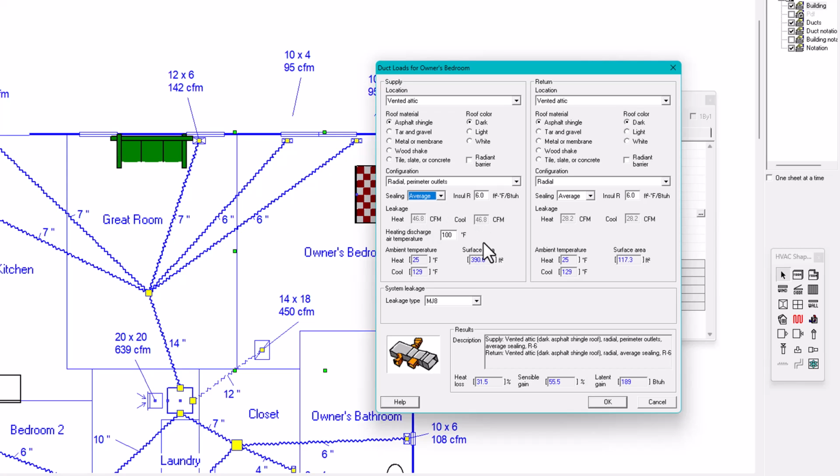And also, what is the insulation value of these flex ducts in the attic? That's also very important. In here it says insulation R6. I wouldn't think that would be a good idea, because in the attic we've got to be careful. But who says that? What we can do is check the energy conservation code, depending on the location. What is the minimum required per location? For example, in New York City it might be different, or in Florida or Miami it might be different. But I wouldn't put a 6, I would put a minimum of 8.